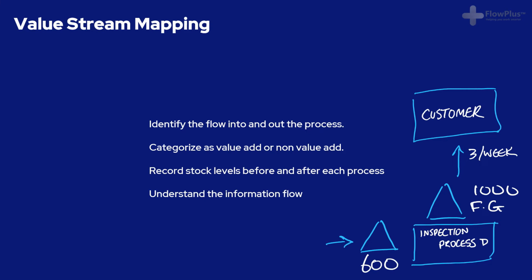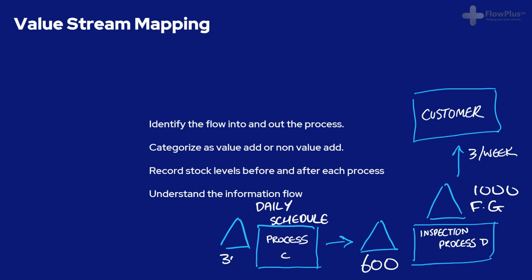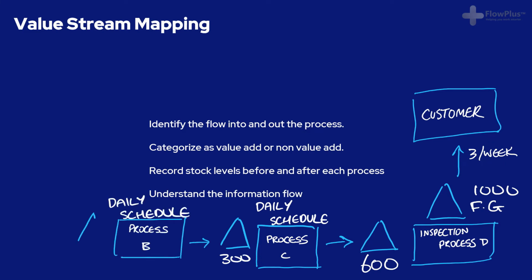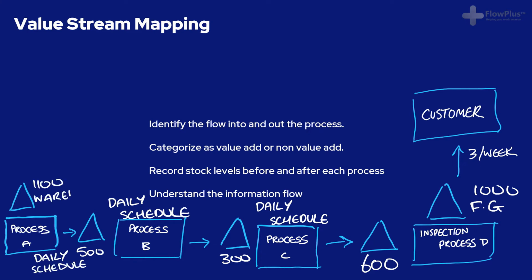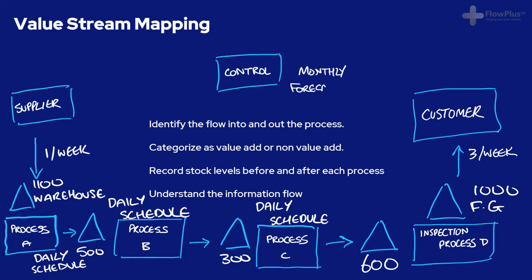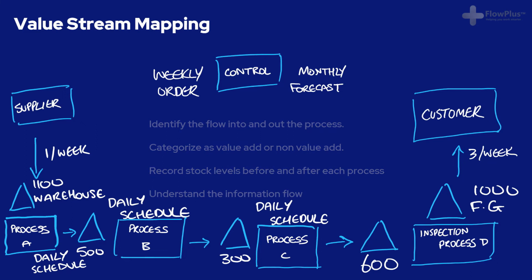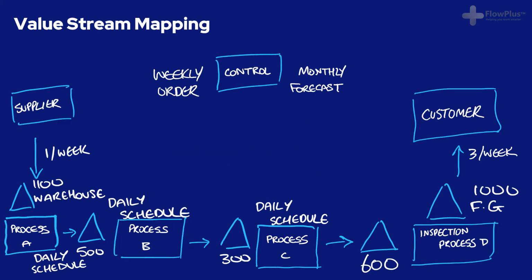When mapping the value stream, be vigilant and ask the operators or team leaders if you're ever unsure. It is important that the information and flow of processes is accurate and no assumptions are made. Often the way things are done is different to what you always thought or how they were meant to be done. You should continue doing this, moving upstream, until you reach the start of your value stream, which is either the arrival of deliveries at goods in or at the edge of your scope.